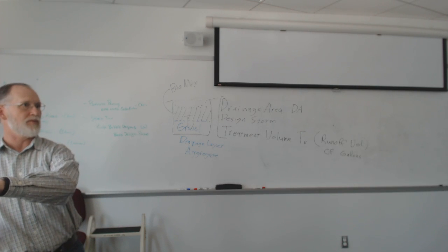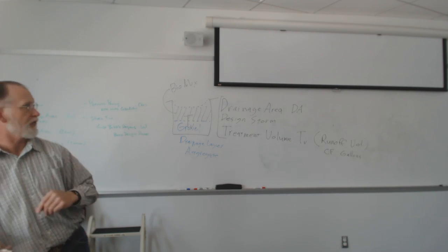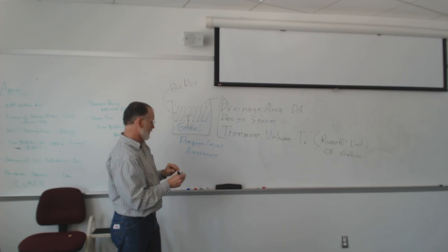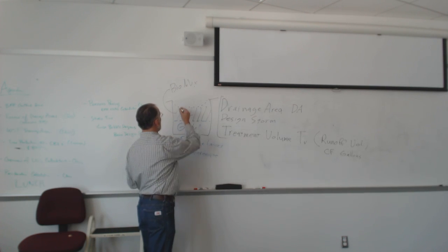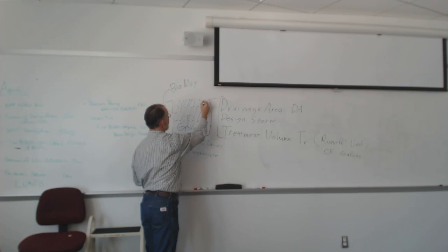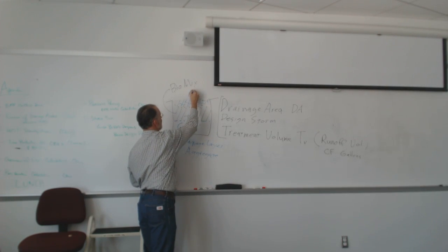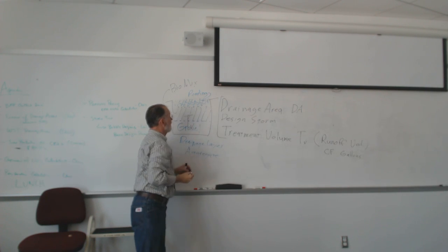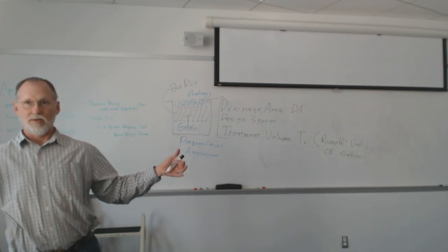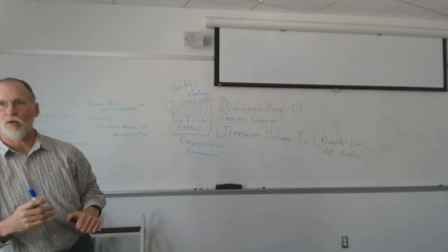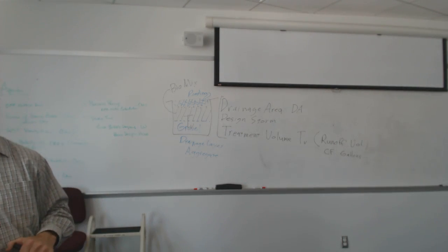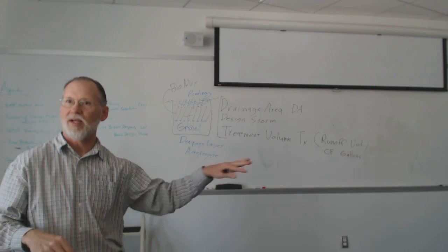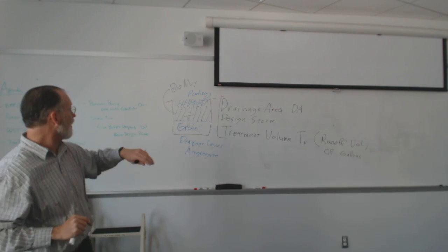As we get into the rain garden, we'll talk more about the specifics of that, and there's a lot of specifications. But in a rain garden, you've got some form of mix here. And then, again, this is typically for rain gardens, you've got this layer up here. It's your ponding layer, right? It's been raining. Your rain garden is designed to hold, say, 6 to 12 inches, which are typical ponding depths. So it's designed such that when it gets more than 6 inches, it goes out in overflow. So basically, when it stops raining, you're only going to see 6 inches in there. That's your ponding level.